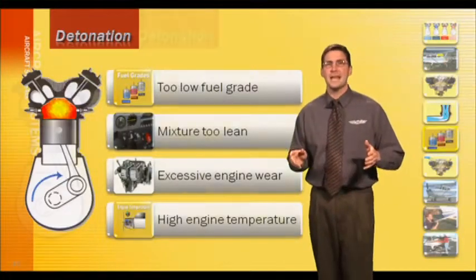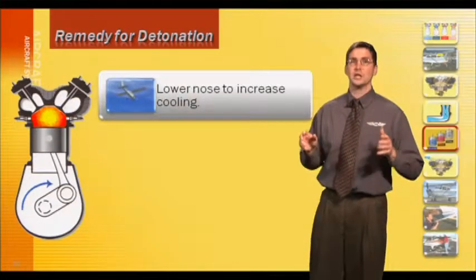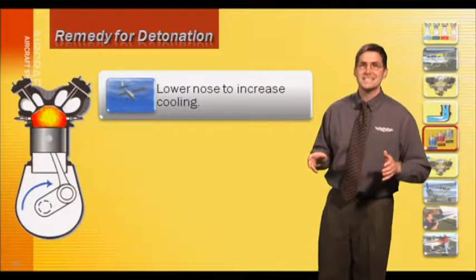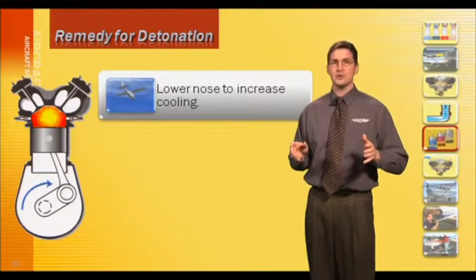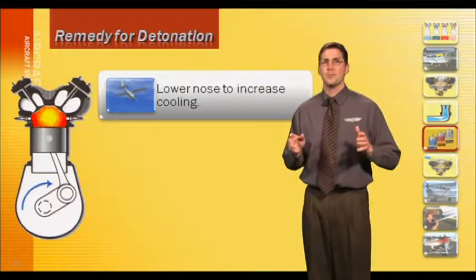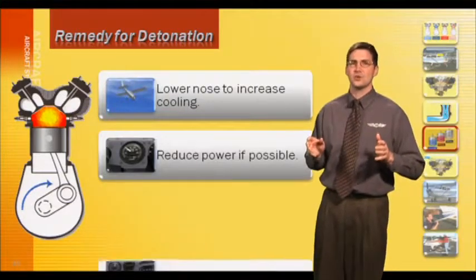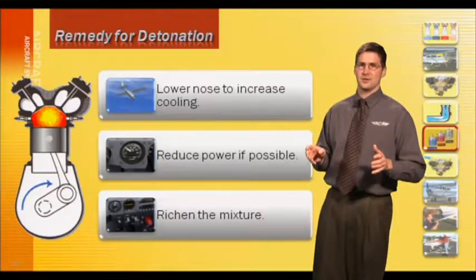If you experience engine detonation during takeoff, lower the nose slightly. This tactic increases airflow, improves engine cooling, and reduces engine's workload. Remember, detonation may cause internal engine component failure.